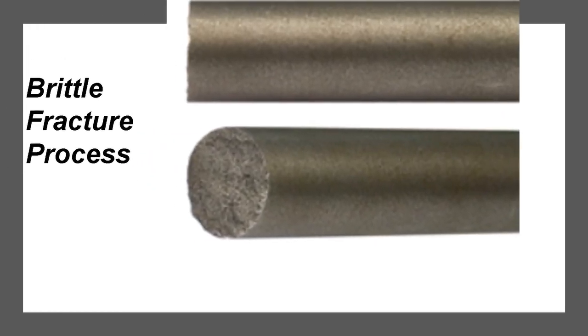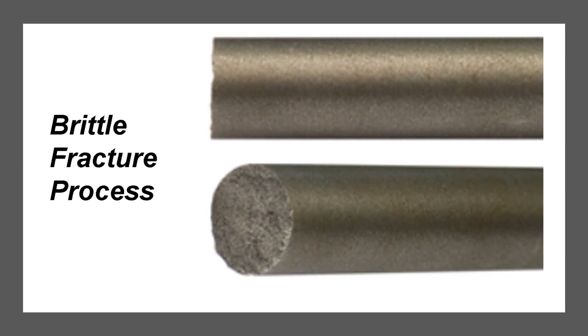Brittle fracture, on the contrary, is characterized by little plastic deformation, and the direction of crack motion is very nearly perpendicular to the direction of the applied tensile stress. The crack in this case is defined as unstable because it propagates rapidly without increase in stress.